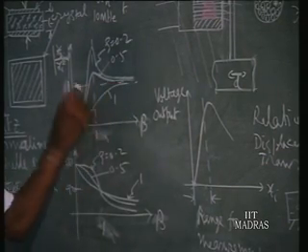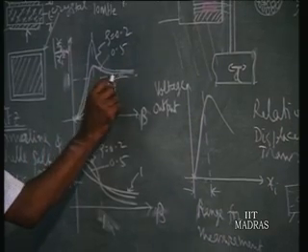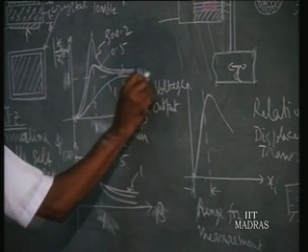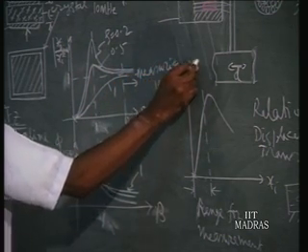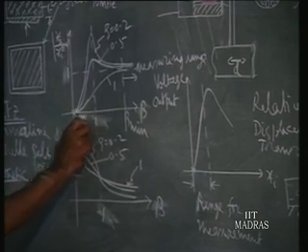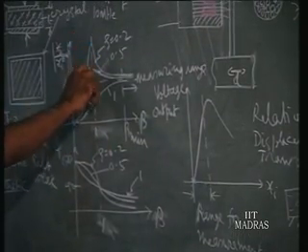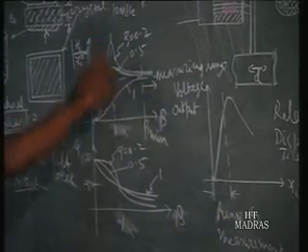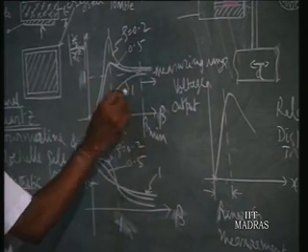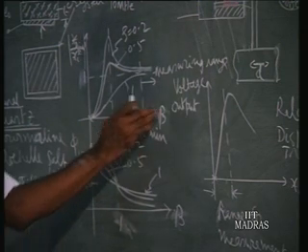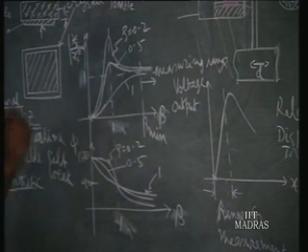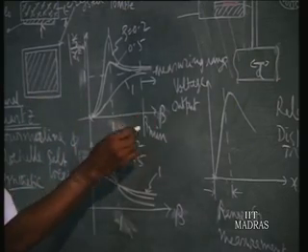And the ideal condition is we get Xo as Xi, that is, as 1. Around 1, this is your beta minimum for the measurable range. From here the measuring range starts, around 1. So you find initially 0, but later on as beta increases, it increases, and when psi is 0, near a small value, you have some oscillations, some peak value, and then again it stabilizes towards 1. 1 is the ideal condition. Only for larger values of beta do you get the measurement. That means the instrument can function, the measurement can be made, only when beta is greater than or equal to beta minimum.